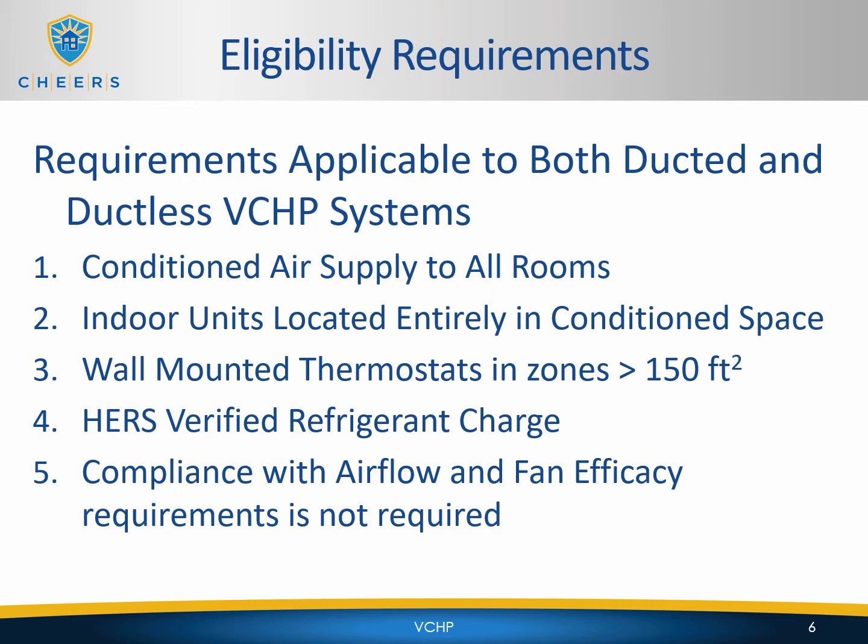First, the system must supply conditioned air to all rooms. The indoor units must be located entirely in conditioned space. You're going to have wall-mounted thermostats in zones less than 150 square feet. And then you're going to have HERS verified refrigerant charge. Now, typically you would expect to have verification for airflow and fan efficacy as well, but compliance with those requirements is not required for this VCHP credit.